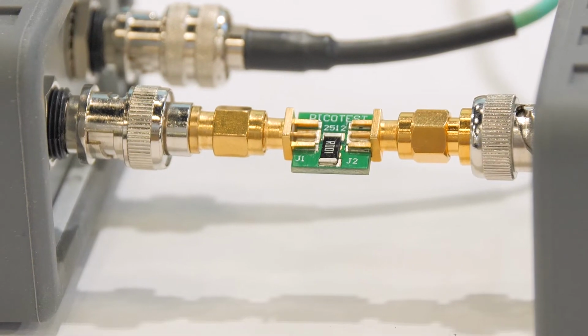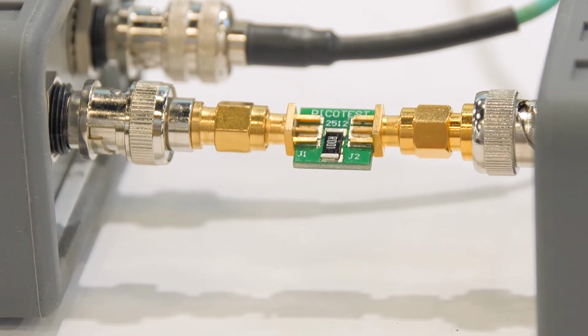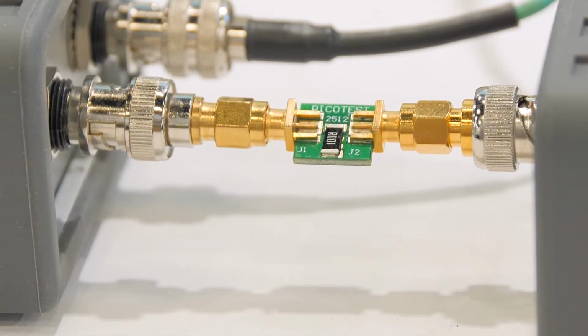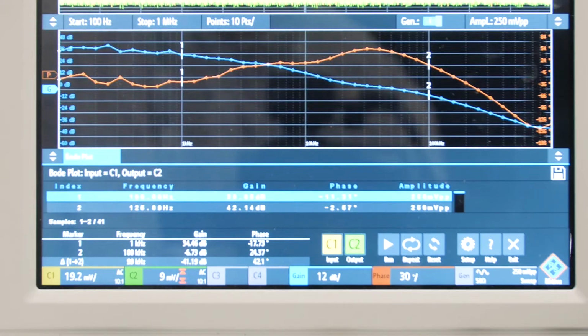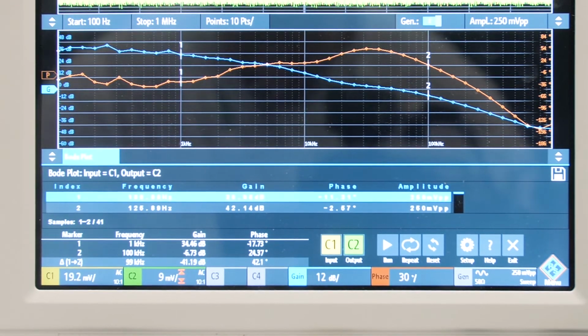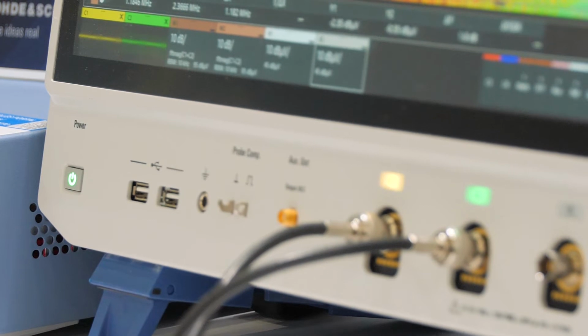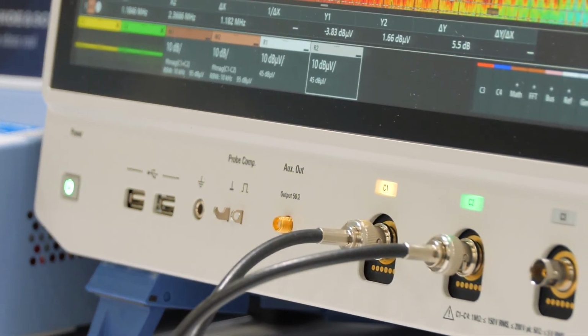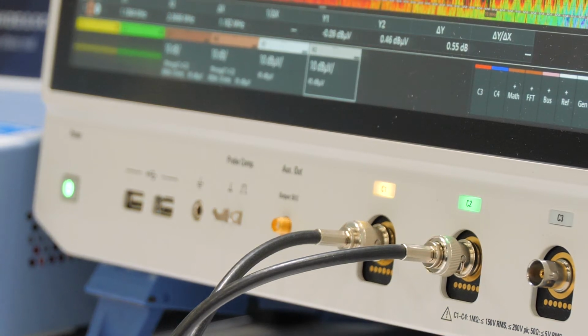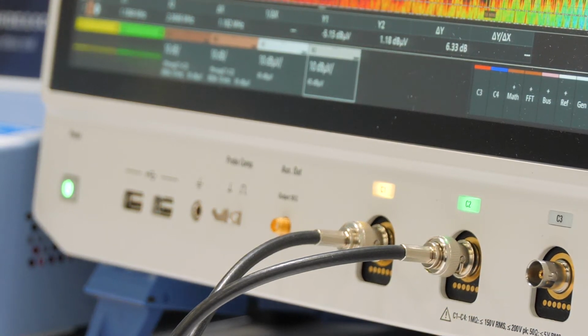A lot of times when engineers are working on power supplies or doing DC power conversion testing, this was normally done in a VNA, and it's called the two-port shunt-through method because you are using two ports on a VNA and some really sophisticated math to determine what exactly your impedance value was. But Rohde and Schwarz enables this measurement now on an oscilloscope, which most designers have on their bench and feel very comfortable with. When you're doing this kind of measurement, you're going to have inherent ground loop problems.